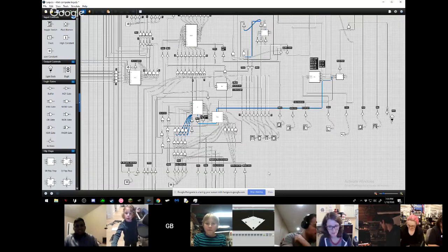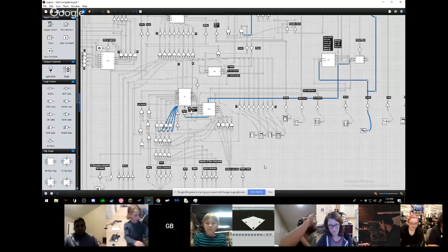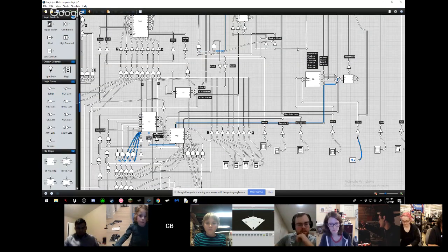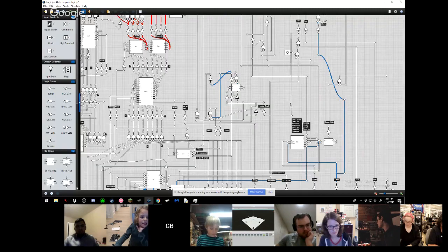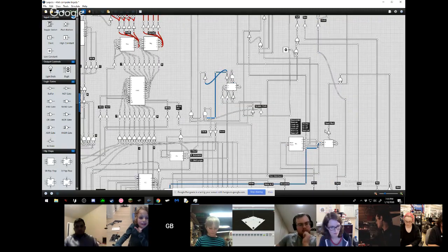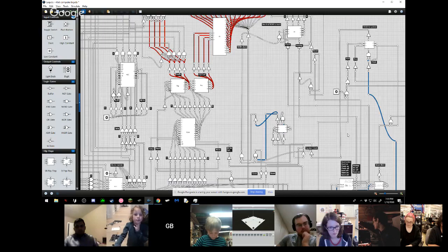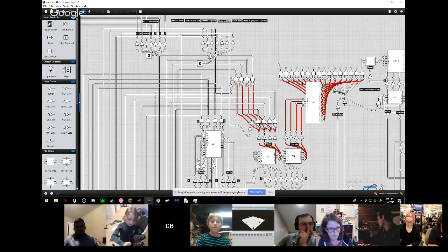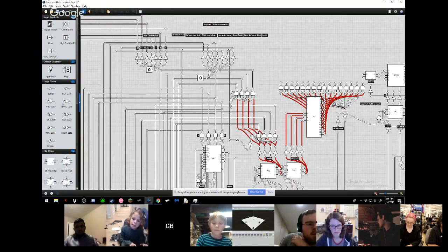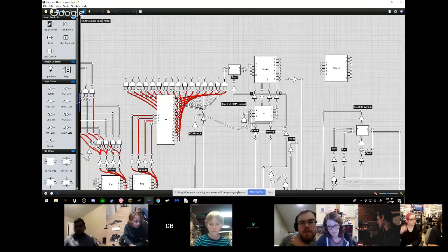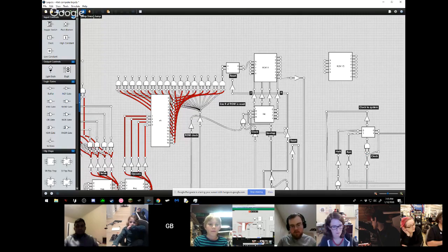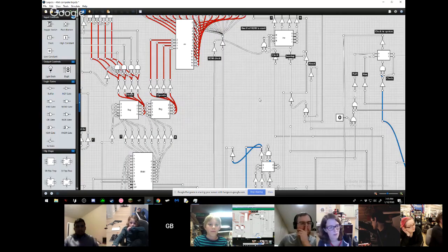So far, all complete. Last time I was here, there wasn't much, but I've done a lot. I've made a bootstrap loader, the registers, the ROM, well, one of the ROM banks, and a bunch of commands that the system can use up here. So far there's one ROM bank, and all it does is a no operation. But because of that, that counts as an operation. So yes, I can use this computer.